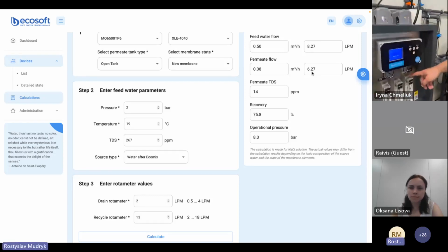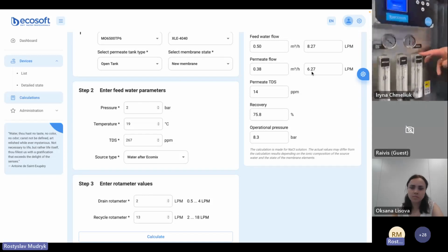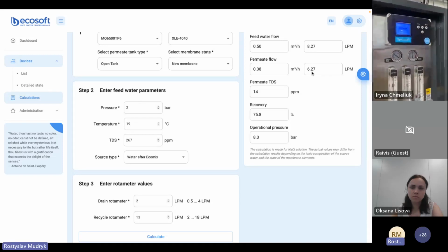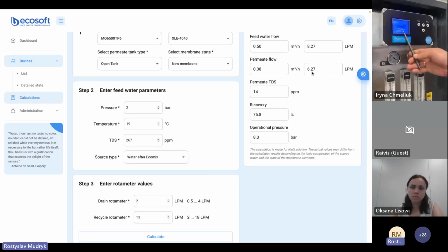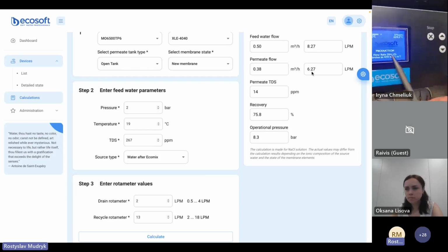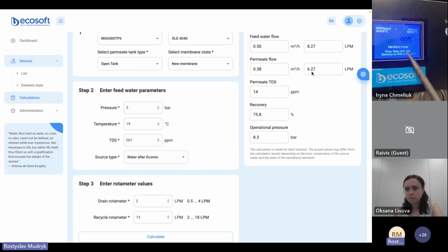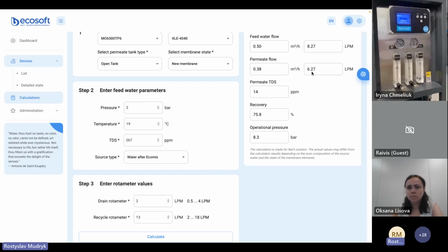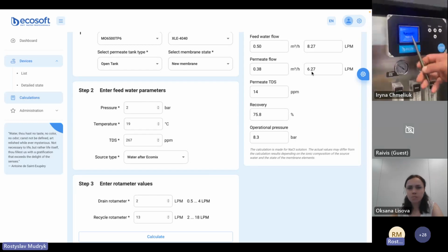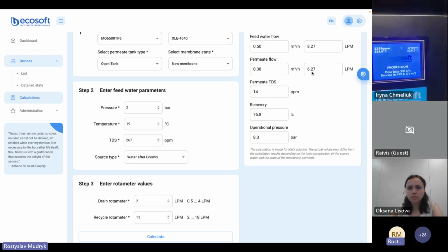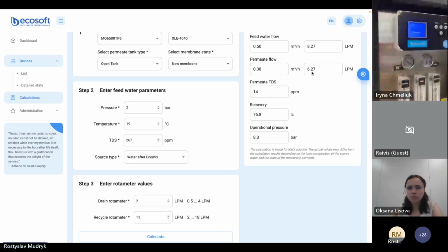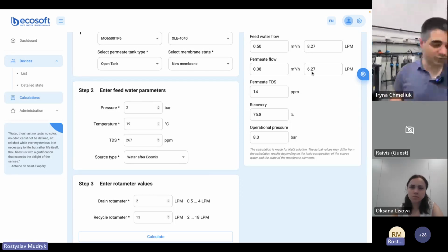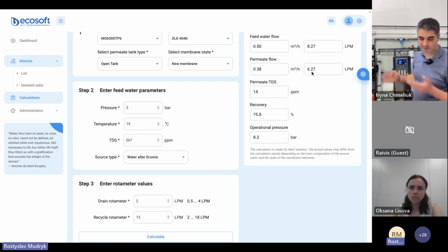So basically, you may read the flow of the permeate both from the permeate flow meter, and also from the controller screen. Now you see that my flow rate is 394 liters per minute. That is exactly the same, or very close. Yeah, we have 380. So we have a 10 liters difference, which is absolutely okay for these settings. So basically, these are the adjustments. So this is how we move these calculations from the aero calculator to the system.